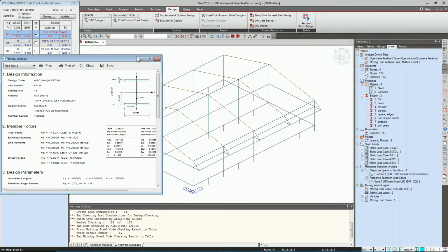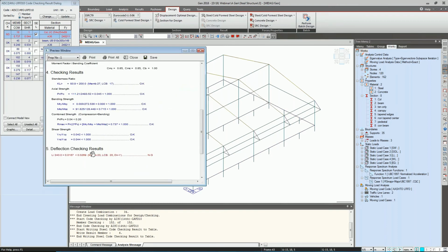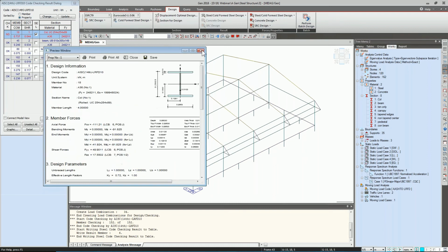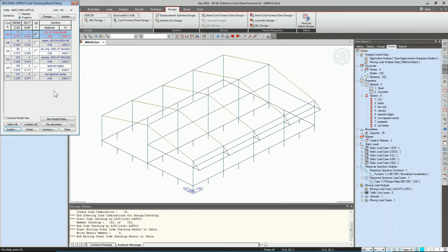There is still deformation. In fact, the deflection has increased. Basically, we need to increase the thickness of the web, and that would be the required thing. In this way, we can go on changing the elements and checking and reanalyzing the entire structure.